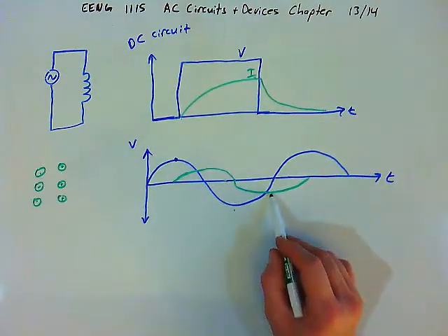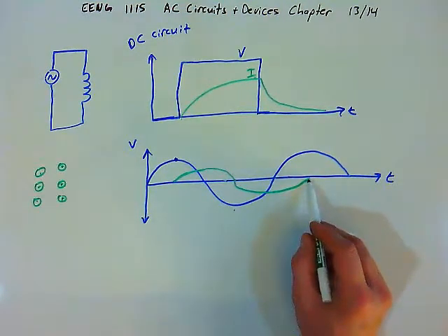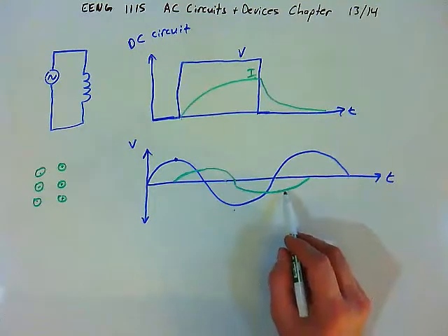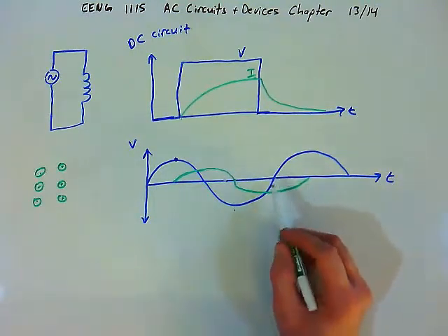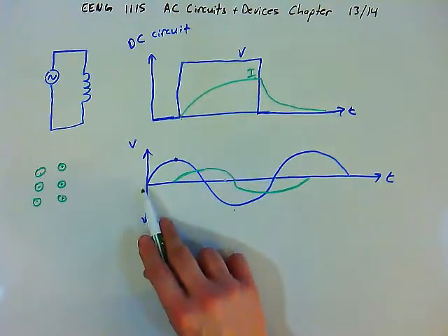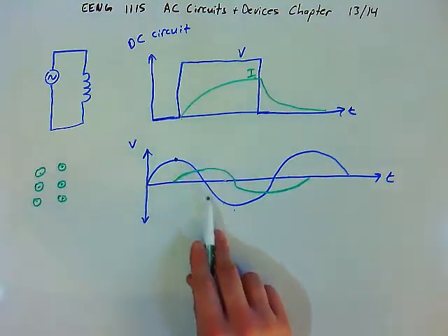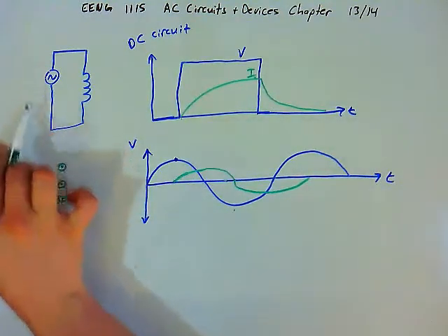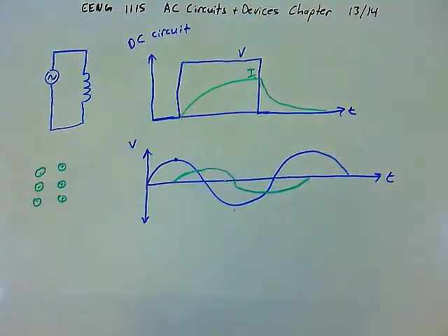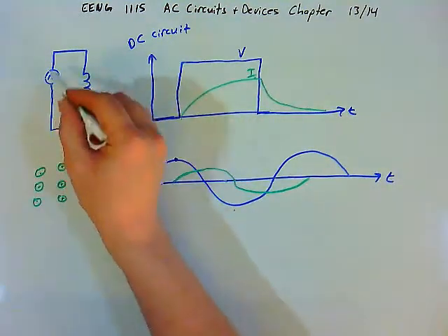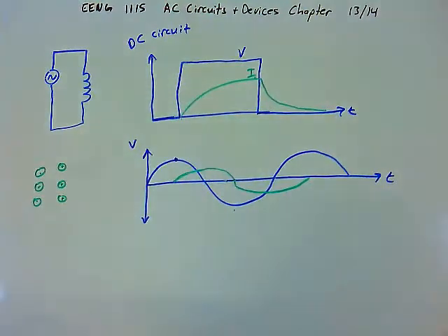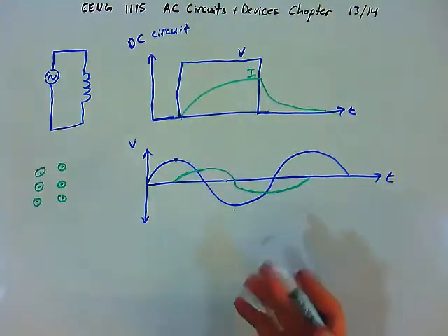the inductor has stored as much energy as it could, and then it starts to give that energy back. And it tries to keep the current flowing the opposite way through the circuit, right? And by opposite, I mean not forward direction, but reverse direction, right? So remember, the polarity of the voltage is constantly switching. Sometimes current wants to flow clockwise through the circuit, sometimes it wants to flow counterclockwise. And so what we see here is a pattern of two sine waves, essentially. And this will continue on forever. And they are 90 degrees out of phase.